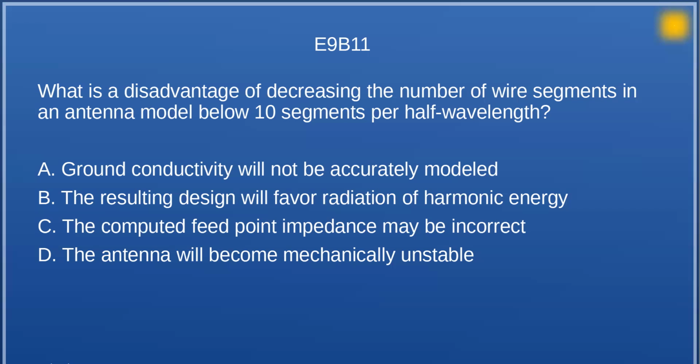And one of the things, when you define the wires, you have to tell it how many segments you want for that wire. So that's where you get into having the minimum. And then you can run the different models. It will show you what the antenna looks like in a straw man sort of thing, and you can do the plots and SWR and all that. What's the name of that? EZNEC. I think it's version 7 now.